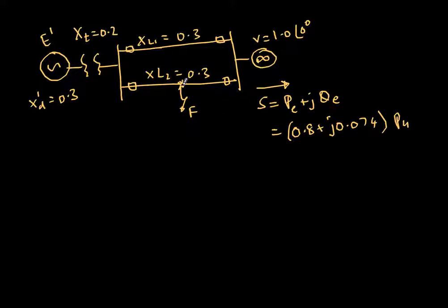Then when the fault is cleared, this circuit breaker and this circuit breaker are open circuited, so thereby this entire line is isolated, and now the transmission network is only one single line, so we still have some power flow going on. So the maximum power transfer limits in each of these cases, that is before the fault, during the fault, and after the fault, will be different. So that's what we'll have to calculate in this.